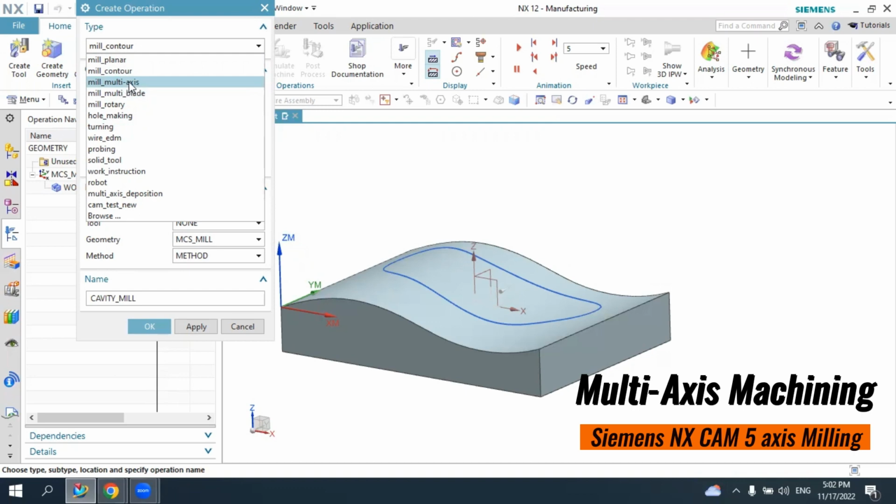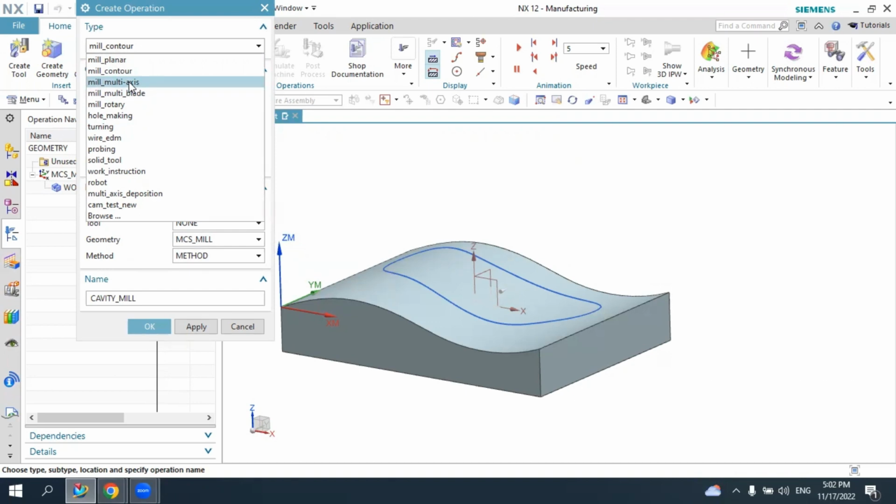If you remember from the lectures, in the 4 and 5 axis milling machines we have 2 additional axes. The table is a rotating table, the rotation of the table. We call it the A axis, and the tilting of the spindle we call the B axis. So it is 2 more additional axes. If the table rotates, it will be a 4 axes CNC machine, and in addition, if the spindle tilts at some angle, it will be the additional axis, so the CNC machine will be 5 axes.